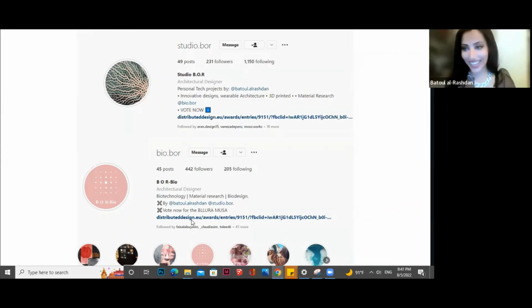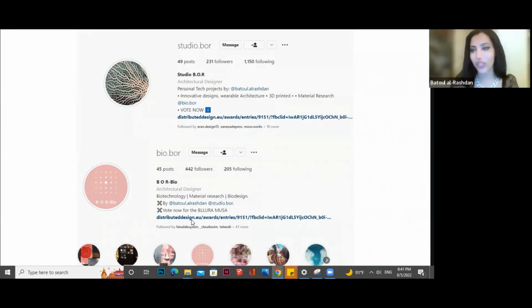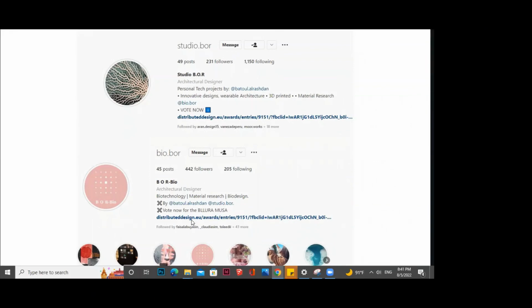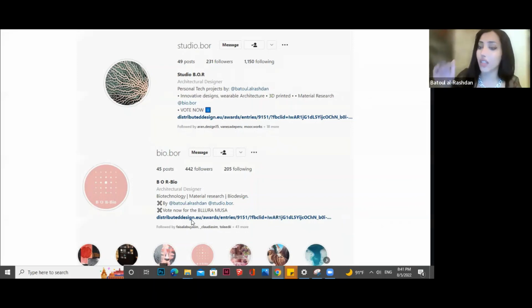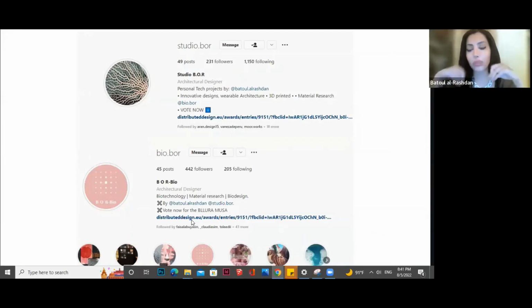You didn't follow up in the lecture because I mentioned it in a slide. I was explaining and I didn't want to get very technical about it. It was through a transition software called Cura. Using Cura, you set the settings of the 3D printer. First you export your model in STL format, and you take that STL file to the software. There are lots of software options. I usually use Cura, which is made for Ultimaker and some other printers. You can't use it on all printers, but it depends on the printer you're using. It has its own slicing software.